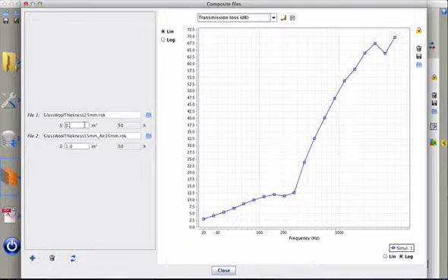So we can see that we can set, for example, a surface of 0.3 square meter of one thickness and a surface of 1 square meter of a system with another thickness and air inside it, and it computes an estimation of the sound transmission loss for this kind of configuration.